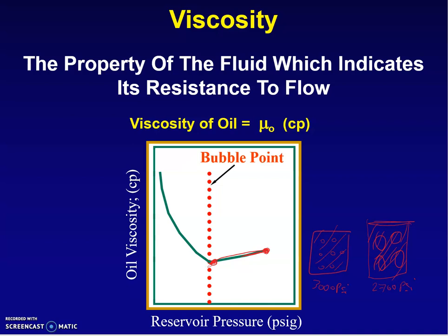And then once you reach the bubble point pressure, this gas will be released, let's say at 2000 psi. It's below your bubble point pressure, let's say your bubble point pressure was 2500 psi. At 2000 psi, you have some oil here and then some free gas. This oil lost gas, which means it's much heavier now, so it is very viscous.